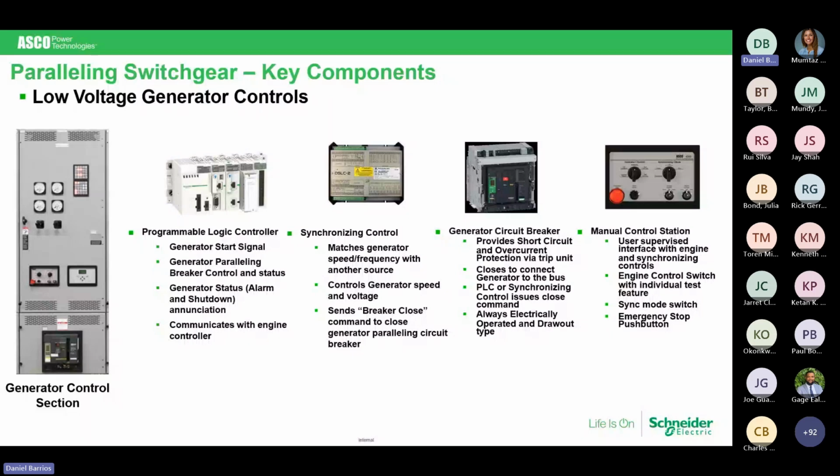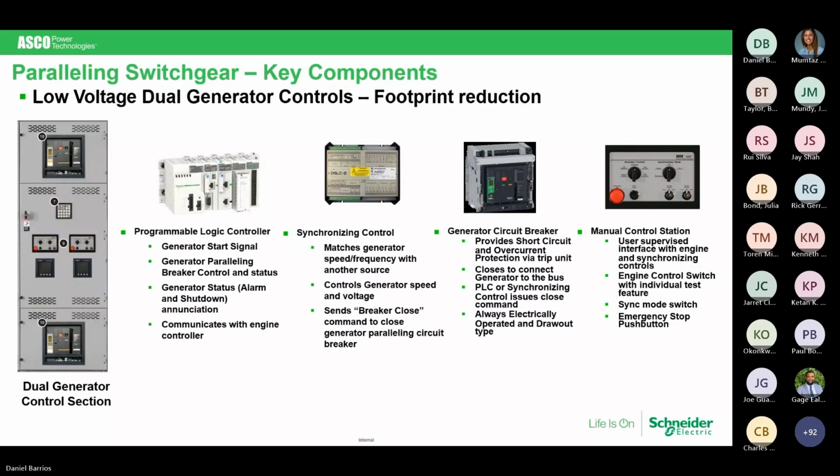The control section here we'll go into, but this is what's operating the synchronizing. You'll also notice that we have a mushroom there, the emergency stop push button, that can be provided in the paralleling gear if that's what your specification, so that you don't need to run out to the generator set in order to punch the emergency stop button.